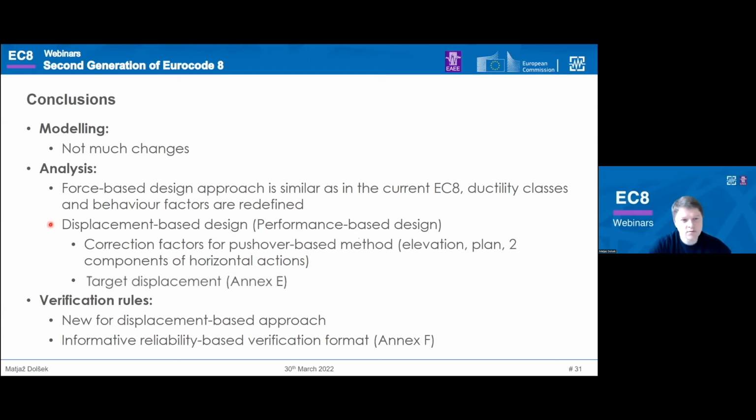For the displacement-based or performance-based approach, the novelty is that correction factors for pushover-based methods are introduced. So there are correction factors for elevation, plan, and the components of horizontal actions. And there is a more general way to calculate the target displacement through nonlinear response history analysis.